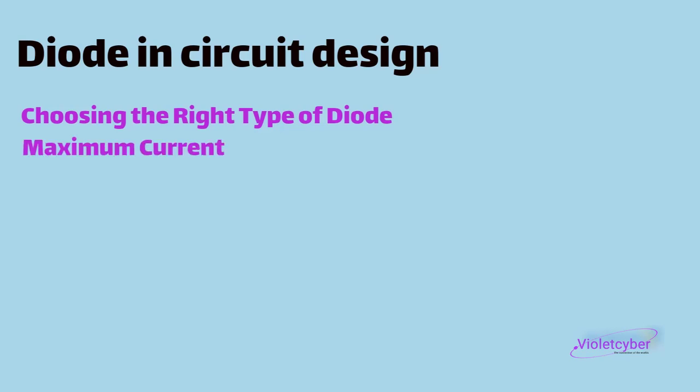Maximum current. Diodes have a maximum current rating specified in their datasheets. Ensure that the current passing through the diode in the circuit does not exceed this limit. Maximum reverse voltage. Diodes have a maximum reverse voltage, known as the breakdown voltage. The input voltage applied to the diode in reverse should not exceed this value, as it could damage the diode.